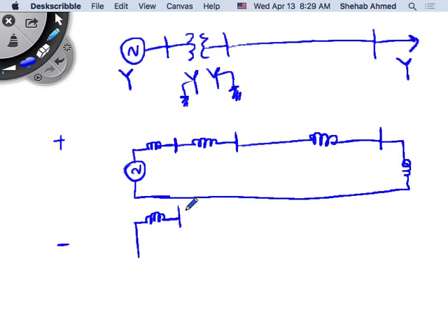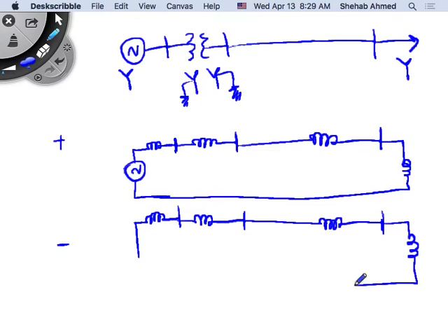If you apply a positive, balanced three-phase voltage across this transformer, but you flip two of the phases, you're applying a negative sequence. What will this power source see? It will see the same series impedance of the transformer that you saw before. Whether you have the transformer connected in positive sequence or flip the terminals, you will still see the series impedance. Ignoring phase shift, forget about phase shift. Here I put star. And then the transmission line, same thing, the positive and negative sequence impedance will have the same value, as we saw from the last chapter. Then the load will be like this.